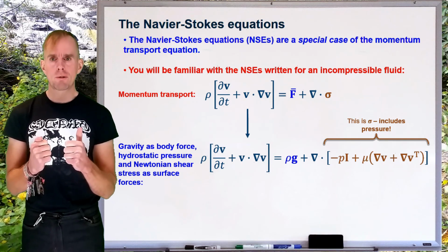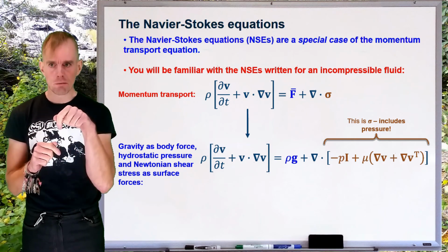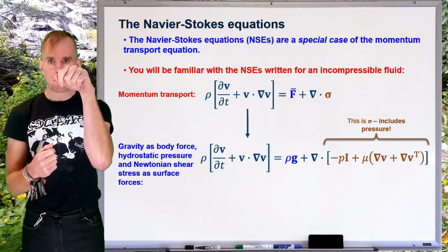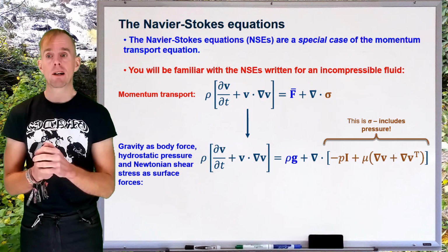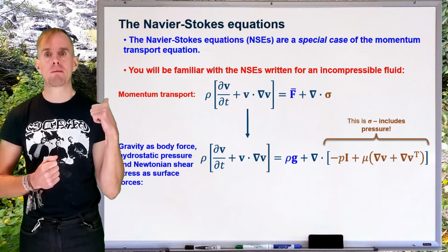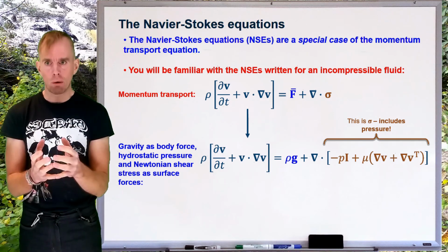So, pressure, of course, will act in a certain direction on a certain face, inwards, hence the minus sign, and in the principal directions, and so in the XX, YY and ZZ directions, which is why we multiply pressure by the identity tensor I. That gives us a tensorial form.